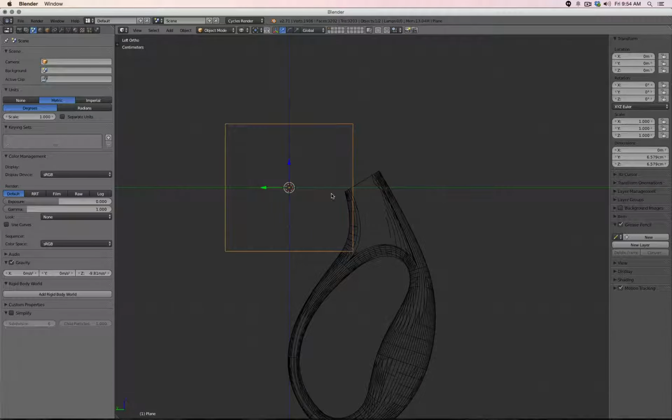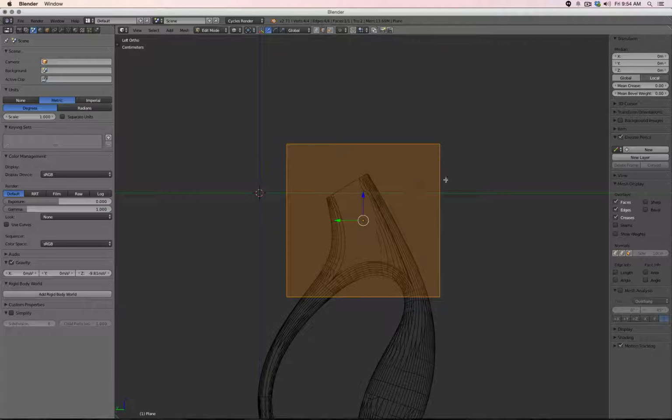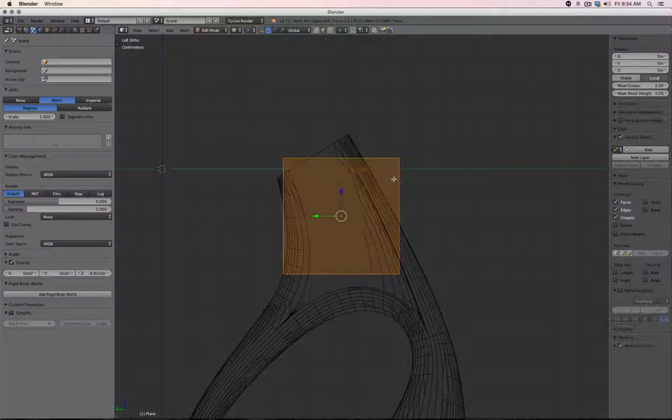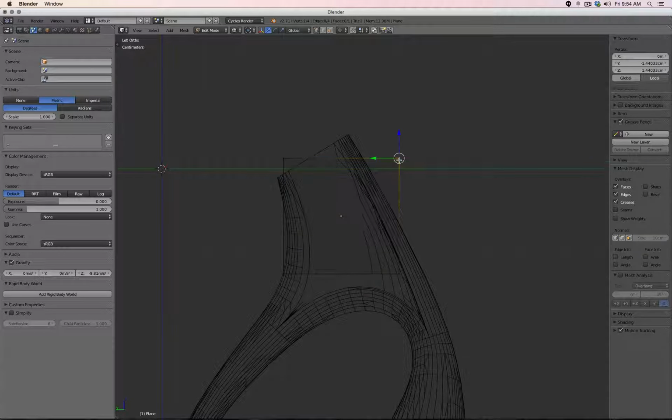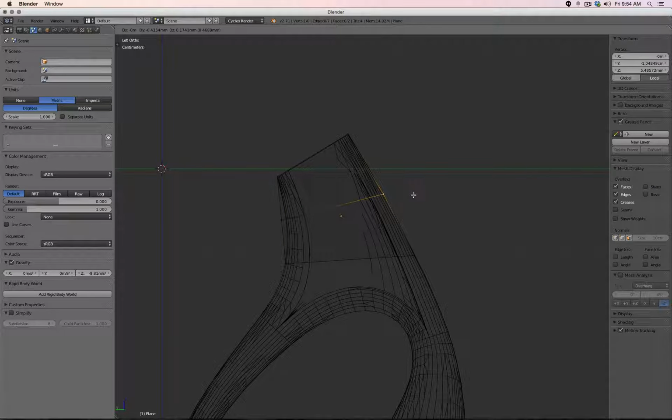Now I can move this whole object in object mode to here, scale it a little bit more with S, and then in edit mode go to CV, and then for example try to see where do I maybe need my base, maybe here. Okay, and now I need a subdivision here, for example, to push this out and to pull this one inwards, and I want a small part of this arc be built.